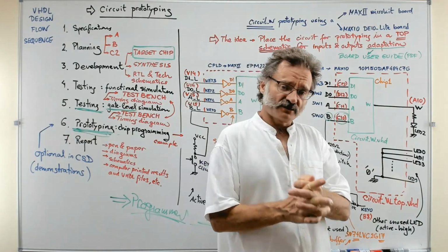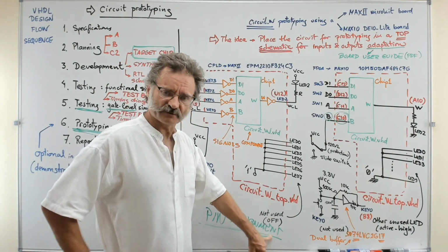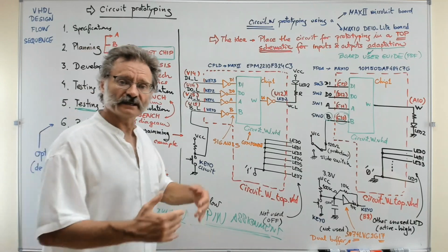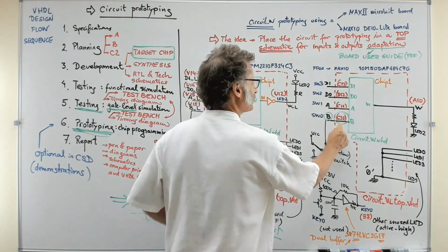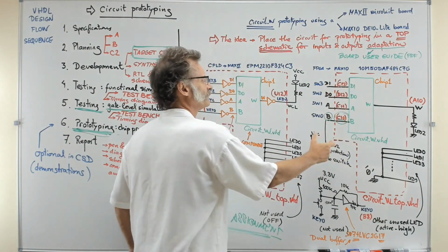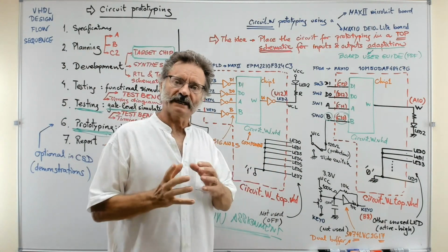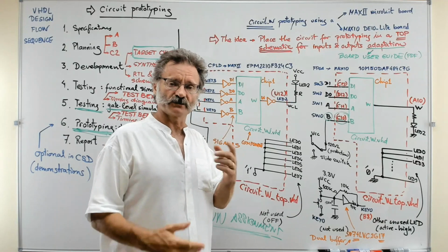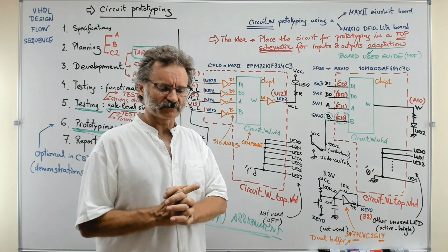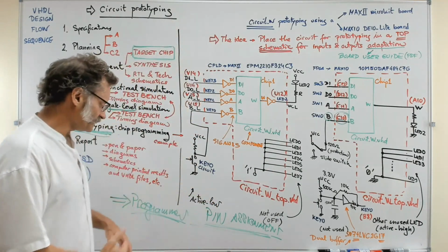That means, as you see, using the pin assignment tool, this is the new thing here, which means basically opening a spreadsheet and simply assigning every input to the corresponding pin. That is what you do, whatever board you have on the table. And once you've done that, you simply recompile it all, so the machine generates the corresponding binary configuration file to be downloaded into the platform. But in which way? By means of the programmer.